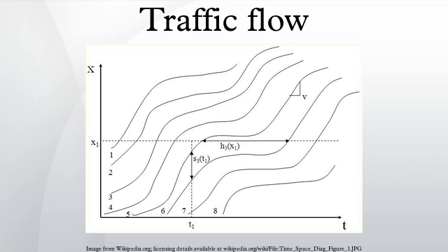Therefore, for as long as vehicles arriving at the intersection are still hindered by the queue, the curve N2 no longer represents the vehicle's actual arrival at location x2. It now represents the vehicle's virtual arrival at location x2, or in other words, it represents the vehicle's arrival at x2 if they did not experience any delay. The vehicle's actual arrival at location x2, taking into account the delay from the traffic signal, is now represented by the curve NA2 on Figure 9.